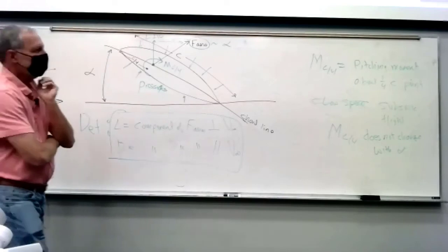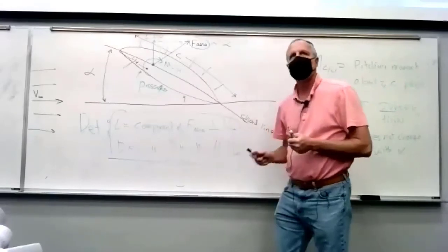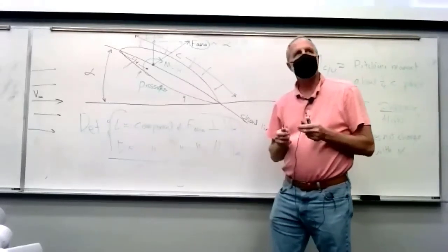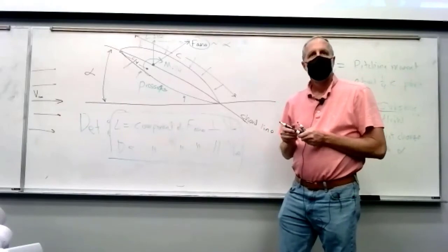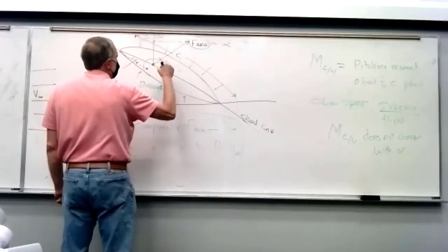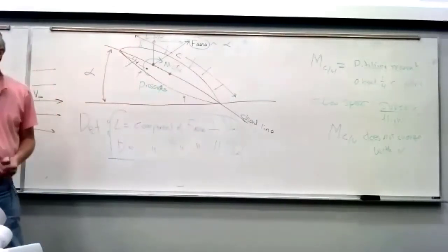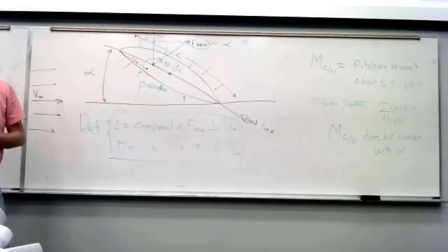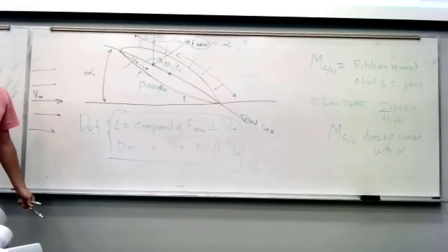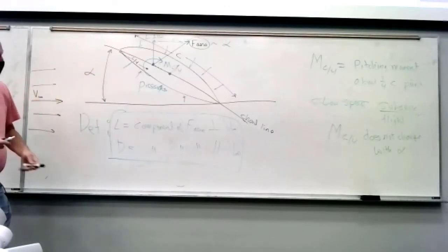Now notice I emphasize subsonic flight. Remember in the video they said, well, as you get close to the speed of sound, the center of lift of the wing moves backward. And so that really happens on an airfoil. This point where the net force acts starts moving backward, and at supersonic flight, it actually acts halfway back. And so that changes this pitching moment, and that's what they were talking about. When they would dive and get close to the speed of sound, the lift moved back and it would cause the airplane to pitch even more down. That's just a phenomenon of the shock waves forming on the airfoil and all of that.